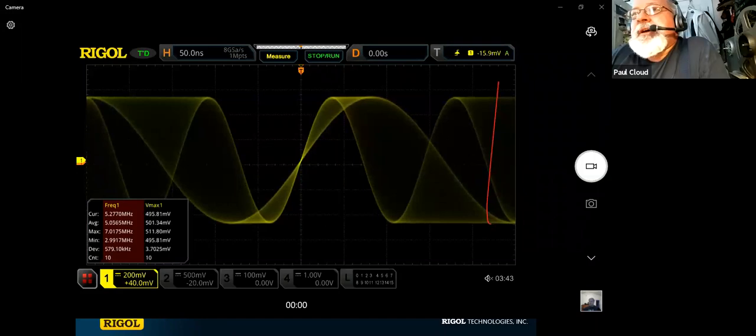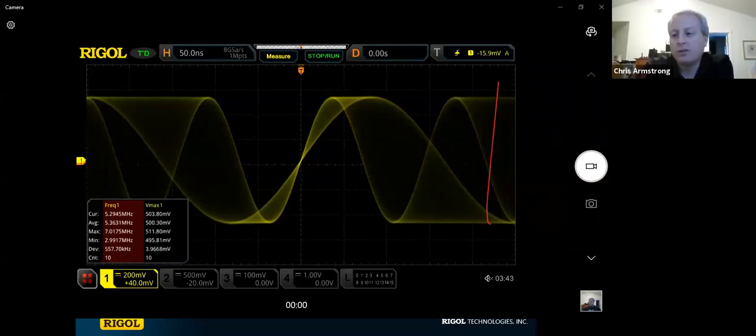And then what's the noise floor on the spectrum analyzer typically? So we usually talk about displayed average noise level, you can get down into minus 160, 165 type area.